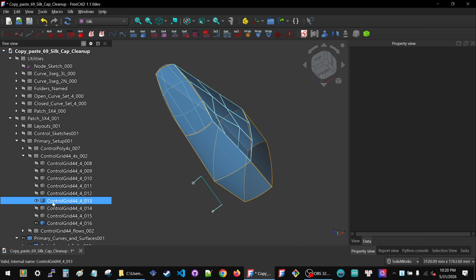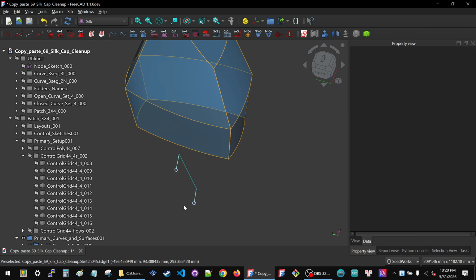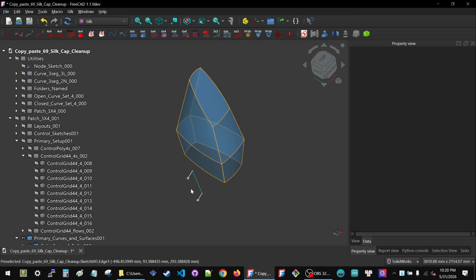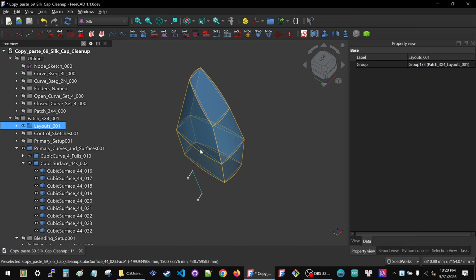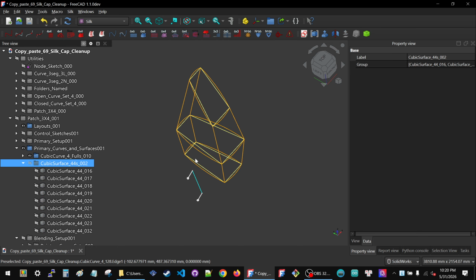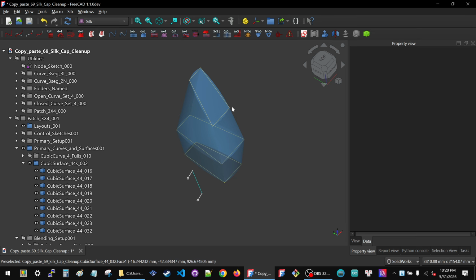Okay, but first actually, let's get this thing moved to its proper position. When we move these node sketches here, we're not going to attach them to the curve. We're going to attach them to the layout. I always choose the shortest data path possible. So temporarily, I'm going to hide the curve so that when I pick the things to attach this to, I'm going to get the points on the sketch of the layout, not the points on the curve.